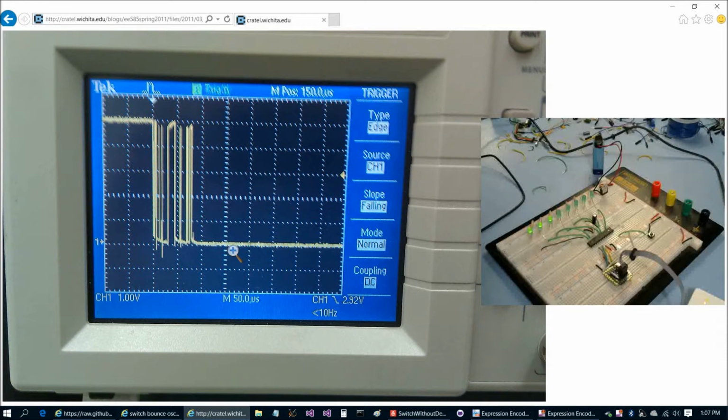So going back to code now, basically when we're going to debounce a switch in software, we have to do the same thing in code that we just did with our eyes. Well, the most basic way to debounce a switch is just to have a wait. So once you get to this point here and the switch is first pressed, you just wait for this amount of time, and then you look for another switch press. The problem is that puts a delay in your program, and as we saw in the previous tutorial on multitasking, if your chip is in a delay, it can't do other things as well. I mean, unless you have a whole bunch of fancy interrupts, timers and counters, etc. set up. But even so, it still is oftentimes not something you can get away with in a significant program to put a delay in your main.